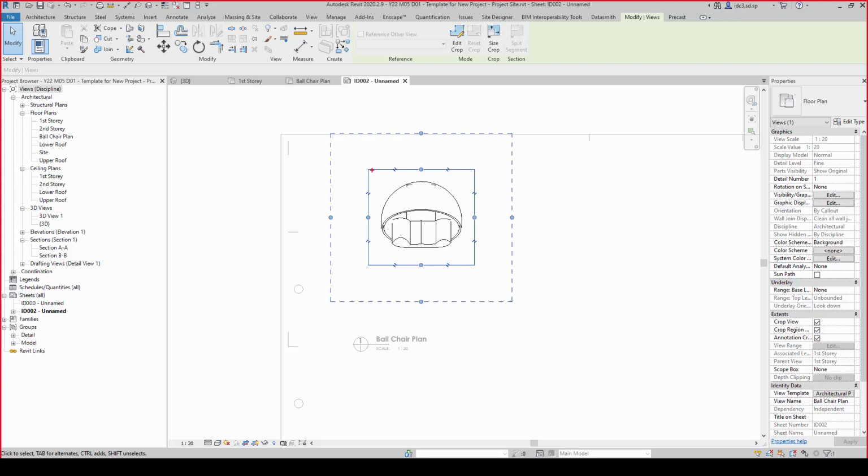Now first of all, you see this continuous line here. This rectangle is almost like the crop window, or like AutoCAD's paper space, the viewport. So we can reduce this. If I reduce this, the viewport, the furniture gets cropped off. Alright, when I expand this, I can see everything.